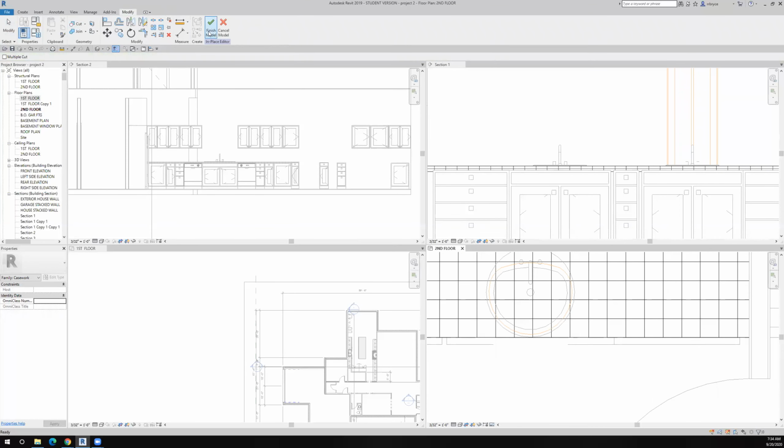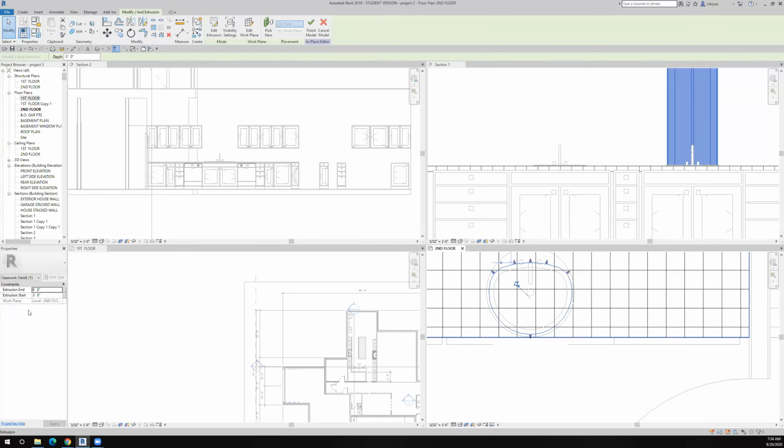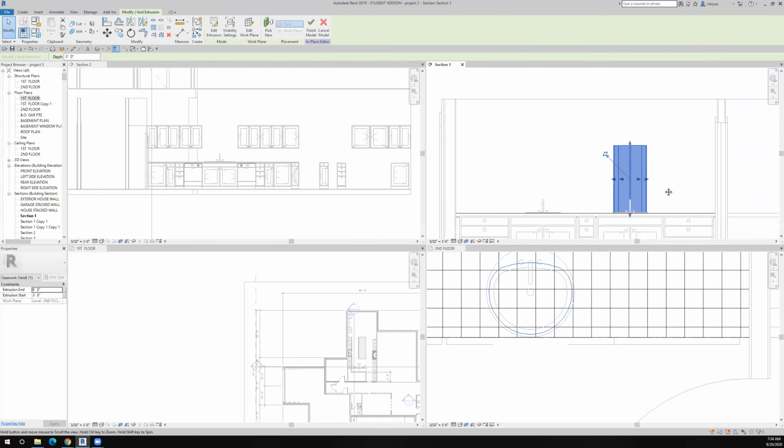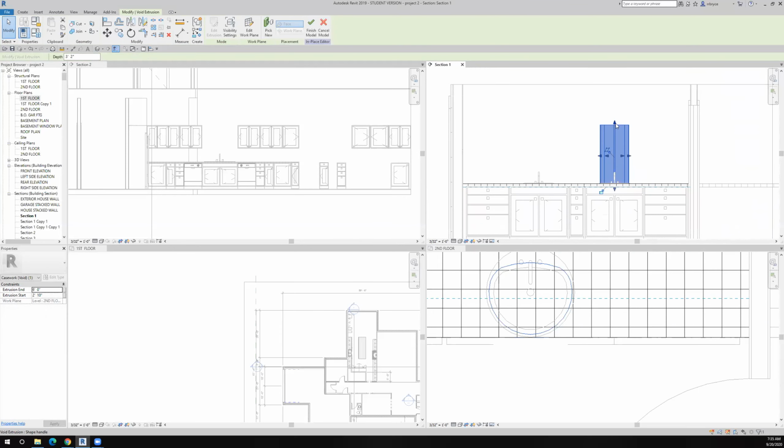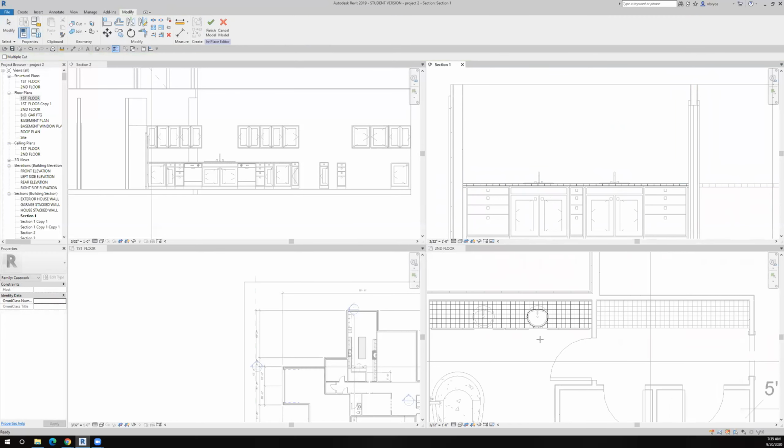And what happened? Oh, I think the settings for that might not be correct. Let's click on that. I might not have the properties of this changed to the height of the mirror. And so you can actually see my void extrusion right now. It doesn't cut through the countertop. So I need it to cut through the countertop. I can just drag it down like that. We don't see the void extrusion, so it doesn't have to be exact. But if I say cut now, it should cut through it. And sure enough, it did. Okay, so I'll accept that